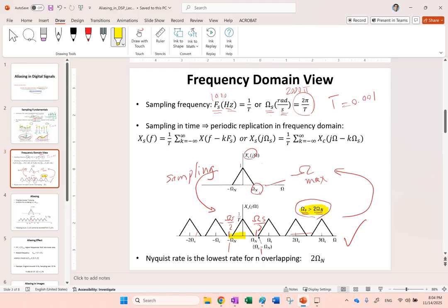And you absolutely see that in this range, what you have is your original signal. So all you need to do is to apply a filter, right? A filter in the frequency domain, which only has a magnitude of 1 in this region, and anywhere else the magnitude of it is what? 0. So here is 0, here is 1, here is 0, right? We call it the bandpass filter. Or if you only look at one side, you might call it the low pass filter.